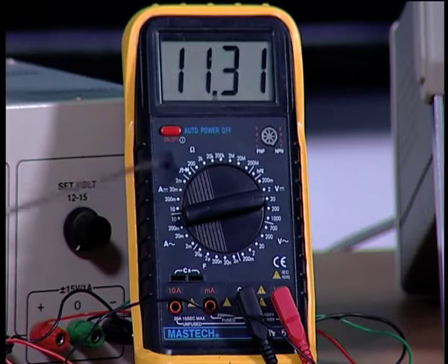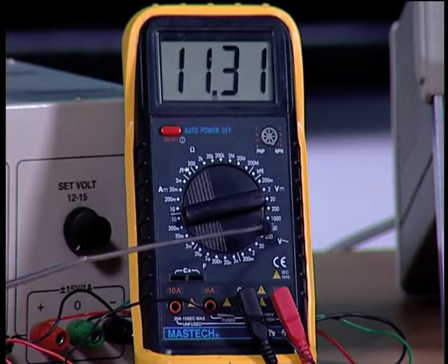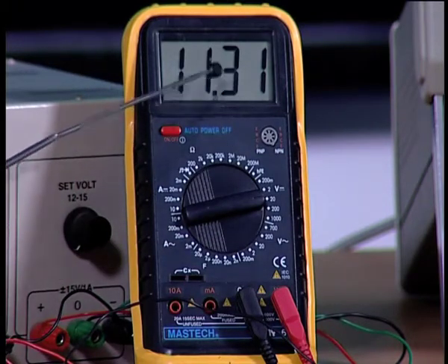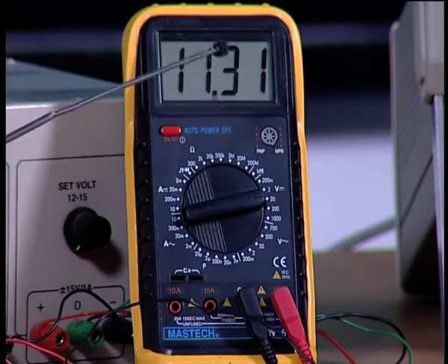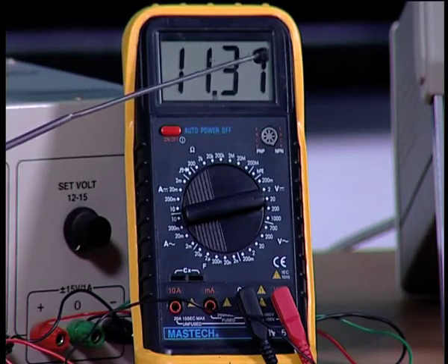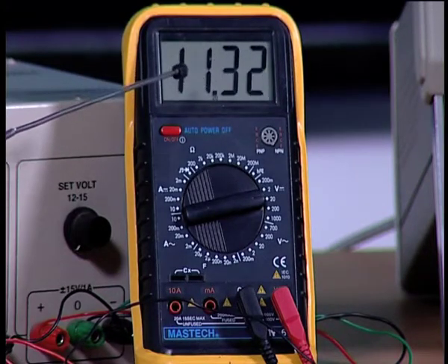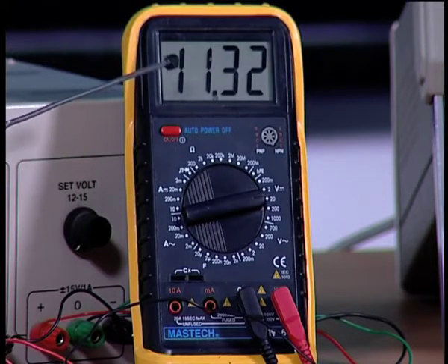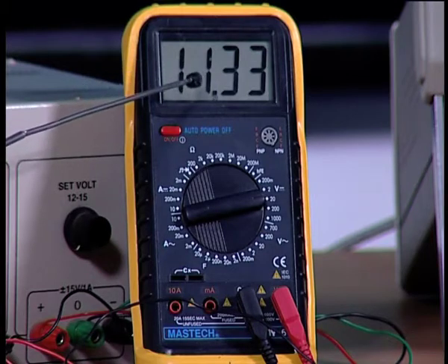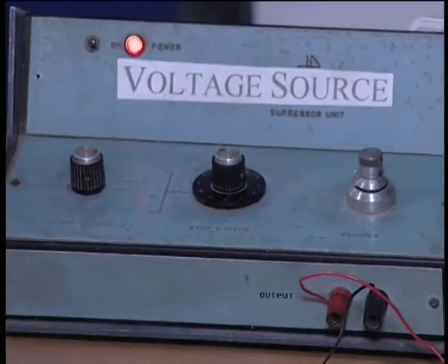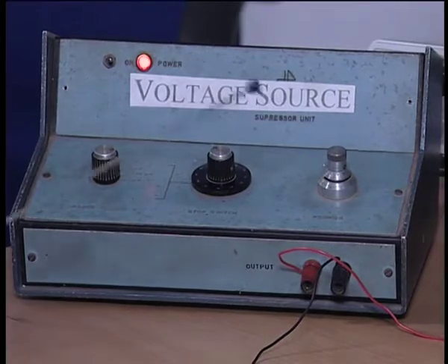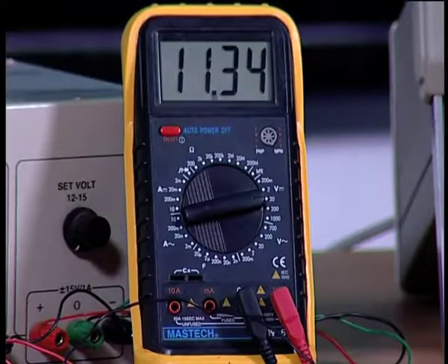The multimeter here is in the voltage mode, and it now shows 11.31 volts. That means it is positive. That means pin number 2, which corresponds to the inverting input, is lower than the 1.2 volts, and therefore I am getting positive Vcc here, nearly 12 volts. If you look at the dial, you can see the voltage here is indeed about 1 volt, and therefore it is less than 1.2 volts, and that is why you are getting 11 volts.